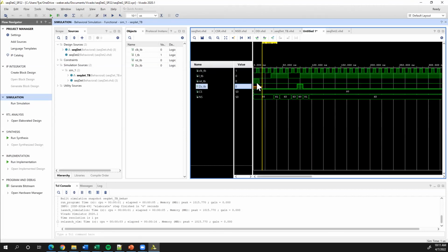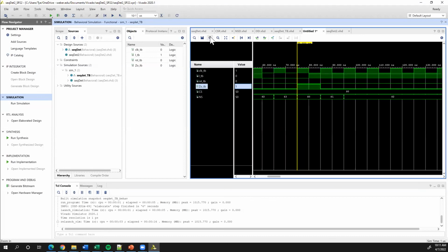So I don't have the output defined in the reset state. I may want to go back and reset that so the output is known, defined. But other than that, we can see it march through the things and make a detection. This detection, if you look at it, unlike the previous one, lasts a whole clock period from one rising edge to the next, because now we're a more state machine. It's a clocked output.